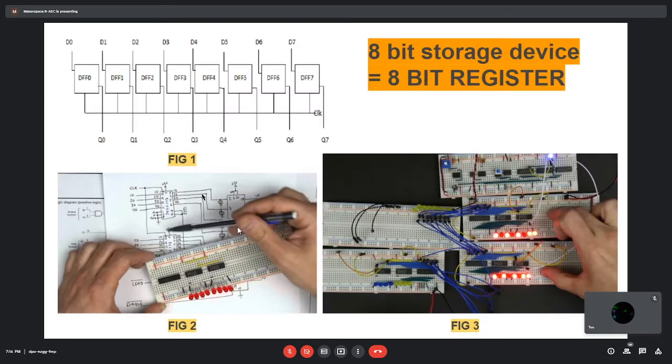Now see what this person has done: he has taken 8 latches. So I'm showing you the diagram. Here we have 8 latches. These latches are clocked, so we can say these are 8 flip flops. These 8 flip flops can store 8 bits, so its name is 8 bit register.